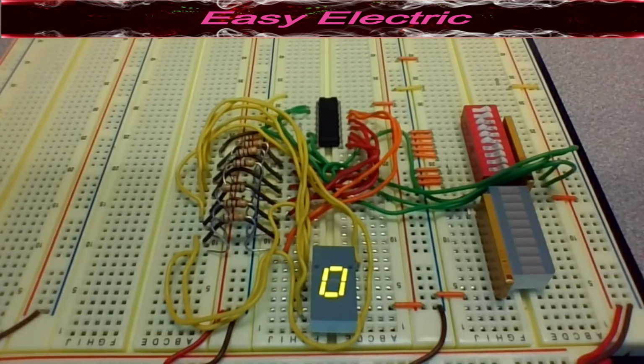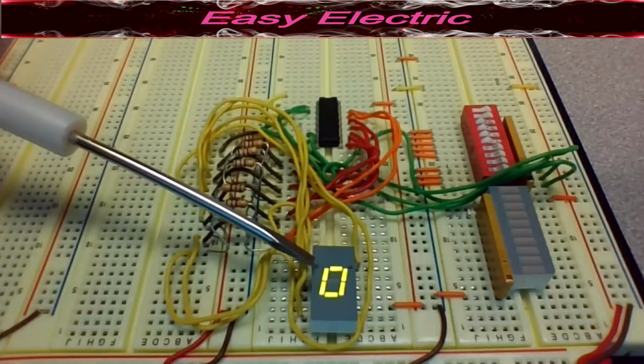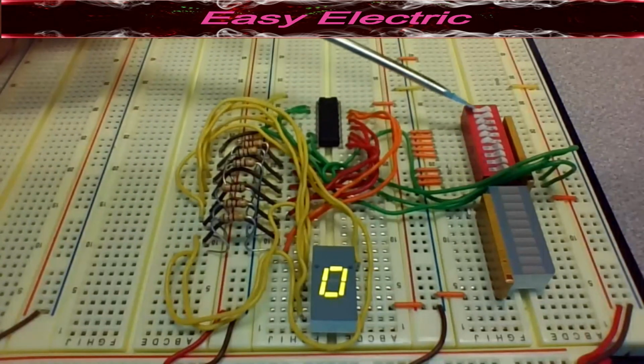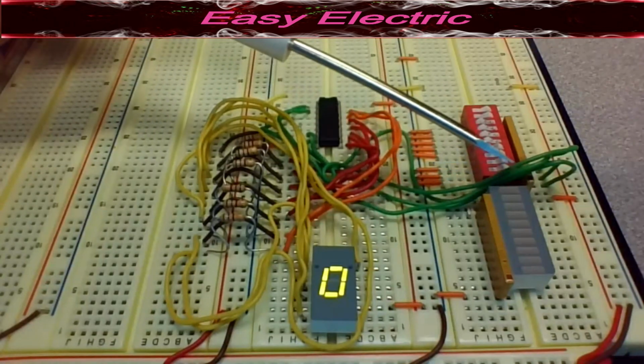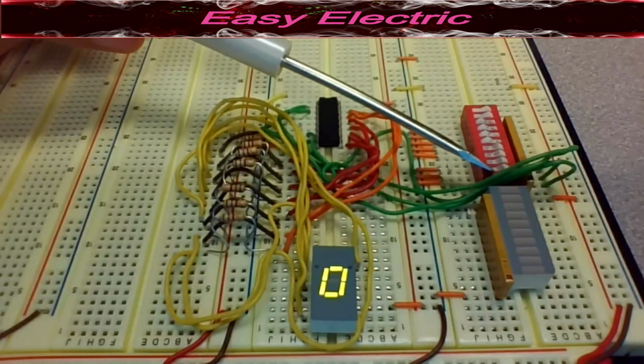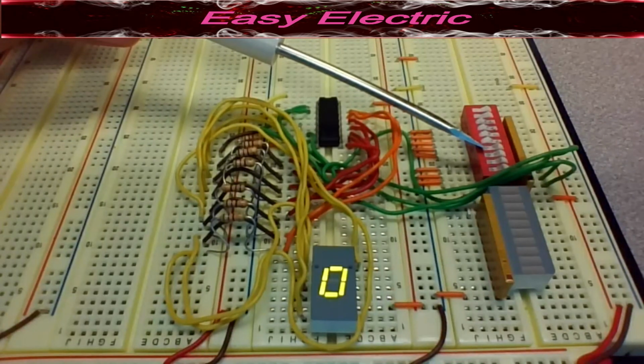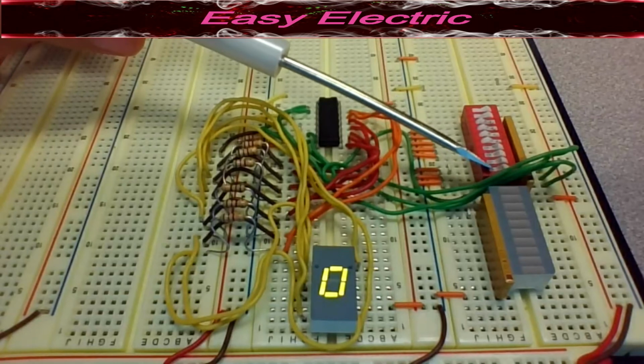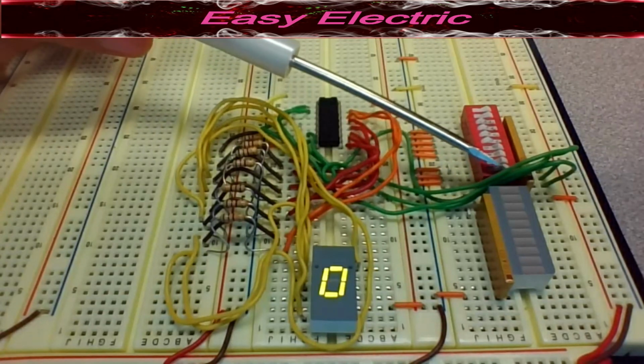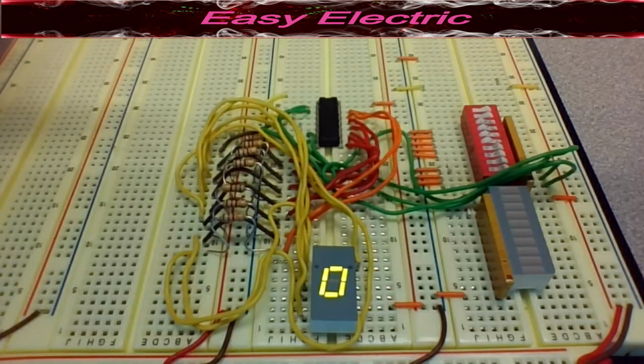This is a BCD to 7-segment code converter. So let's see what we have on the circuit. As you could see here, this is a BCD to 7-segment code converter. The number is 74LS47. So you have the 7-segment here, and on this side, we have our test bench. We connect 4 BCD inputs and give the 0, 1 through these 4 switches that you see here. Whenever you switch to this side, the input is 0. Whenever you turn to the other side, it will be 1.